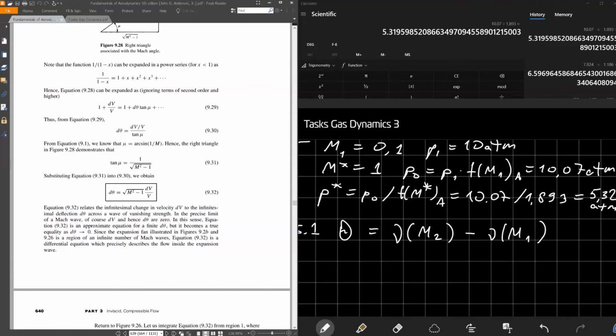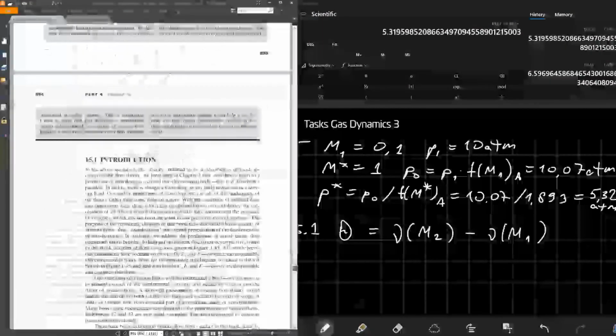Basically, because physically we cannot have such a flow structure in the subsonic regime, and we cannot have Prandtl-Meyer flow in the subsonic regime, and also because this equation has no solution if Mach is less than 1, so it will be negative under the square root, and you will not have a real solution. So mathematically not possible, and physically also not possible.